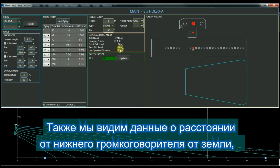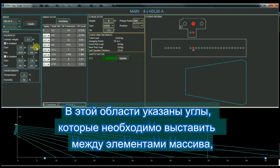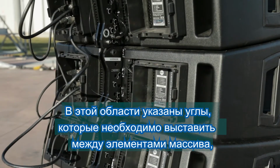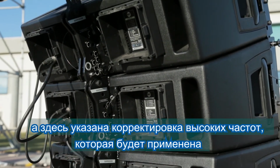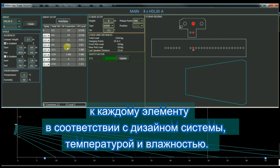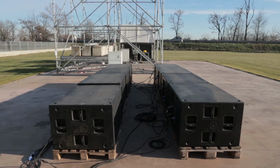There is also the last speaker distance from the ground, so with the laser meter we can be sure to achieve the right height of the clusters. In this field we see the angles we have to set among the modules, and here the HF correction that will be applied individually to each module according with the design, temperature and humidity. Be sure to set the system according with this data.